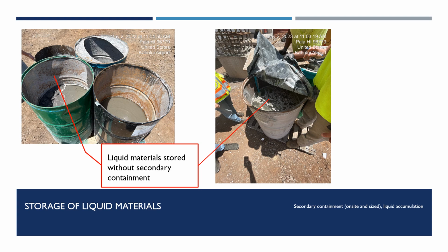Secondary containment measures are sized to accommodate the entire volume of the largest container that will be stored. If there is liquid accumulation within the spill pallet or container and another container spills, there is a risk of overflow.